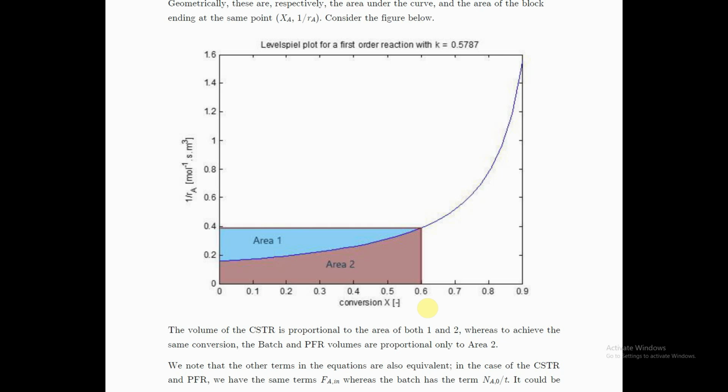So you are stuck all the time at one low reaction rate in that CSTR, and that shows up by needing extra volume. You need a bigger reactor for the CSTR because you've got a low concentration, so you need to fill that reactor with more material, with more mass. You need more mass in that CSTR because you have in effect a lower concentration.